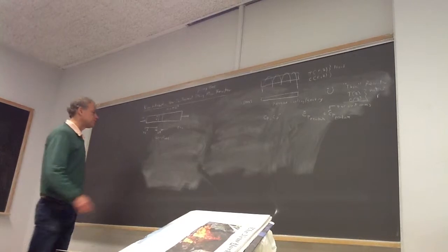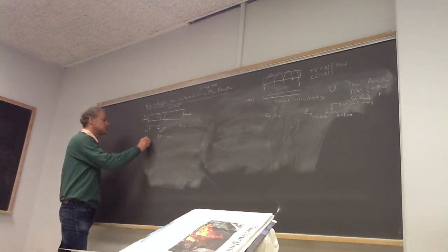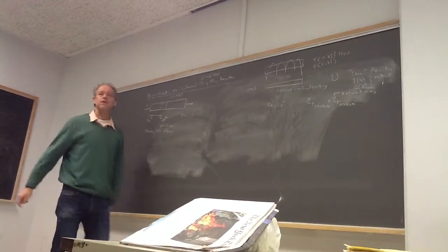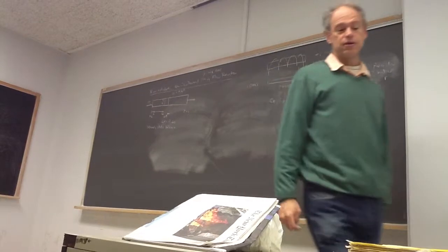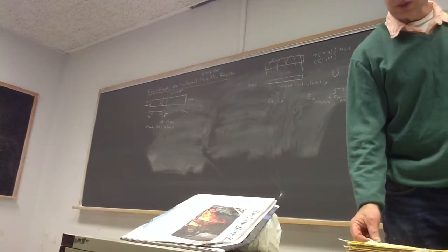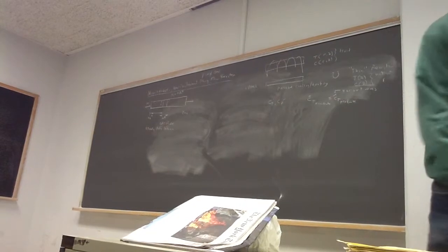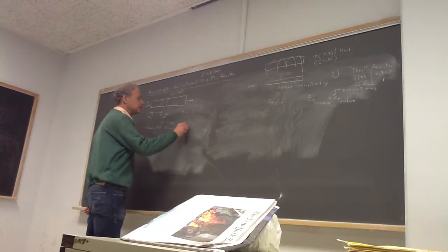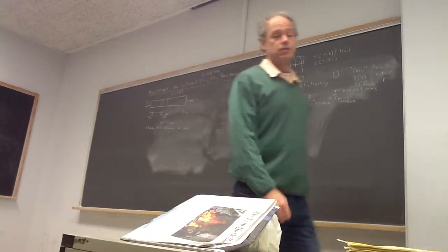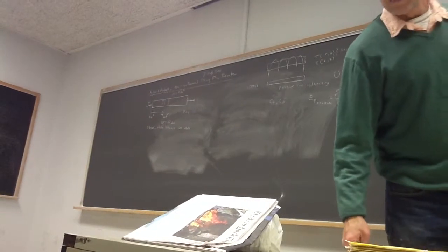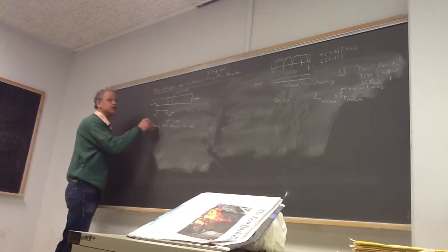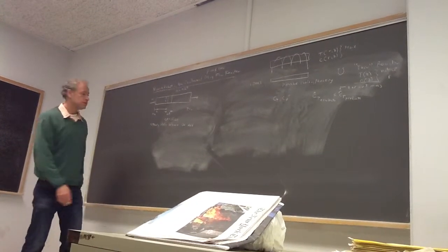So now I'd like to do a steady-state mass balance and heat balance on this reactor. Are there any questions on what we're going to do? We're going to do the balance on delta V. All right, so let's start with the mass balance since that's easier. What is the general equation of chemical engineering? Rate of accumulation.